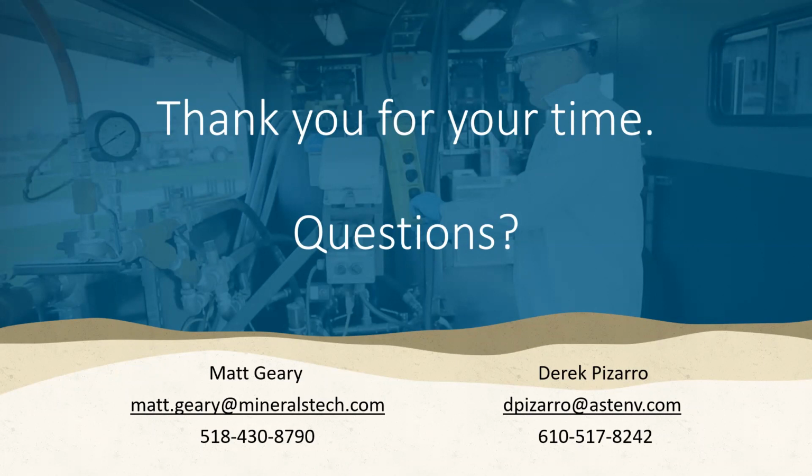Further, what we're doing at the request of various landfill companies is every time we change out media on an ex situ pump and treat project, we bring some of the media back to our lab, and we're doing SPLP and leaching on the spent media. So this is media that's completely loaded up with PFAS, and we're still coalescing that data.